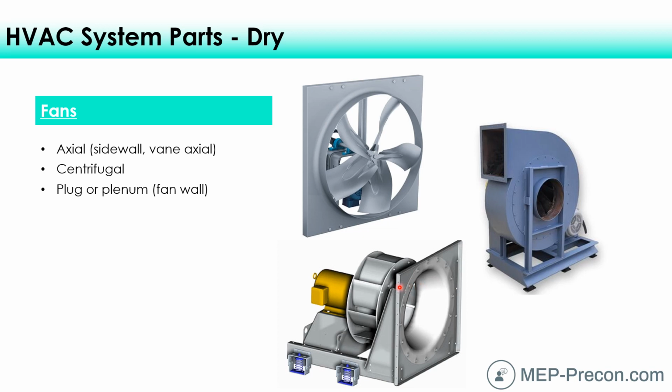or I should say a lot of depth within an air handler, so you can reduce the length of an air handler and make it not so big and expensive with a lot of the outside casing of it. Also, a fan wall provides some redundancy in case one or two motors go out. You still have some other means of providing some air in that space, which is probably going to be okay if you're not at the design peak load conditions.